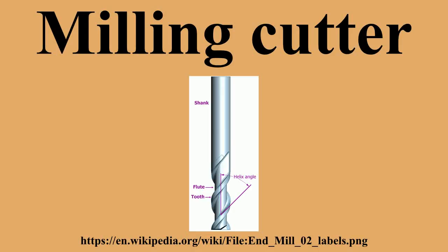Most fly cutters simply have a cylindrical center body that holds 1 tool bit. It is usually a standard left-hand turning tool that is held at an angle of 30 to 60 degrees. Fly cutters with 2 tool bits have no official name but are often called double fly cutters, double-end fly cutters, or fly bars. The latter name reflects that they often take the form of a bar of steel with a tool bit fastened on each end.